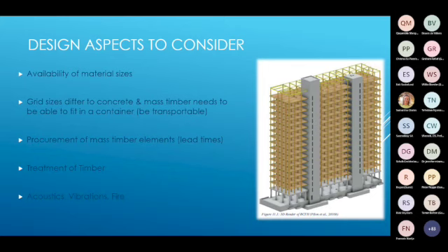Something that the architects are also aware of, and that's going on to my next point, is the column spacing is quite different for a mass timber building to what it would be for a concrete or steel building. The reason being that we don't want to span too far with the CLT floors, and we generally try and limit them to 6 meters for commercial spaces, and that would typically be a 300 thick CLT slab, 3 by 6.